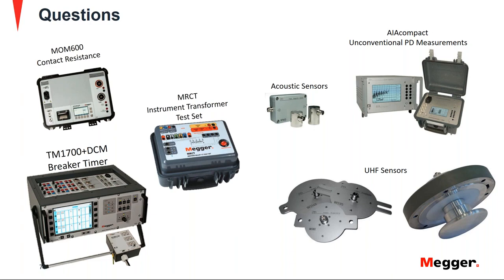Charles, in regards to PD testing on GIS, is online more accurate than manual testing? So I assume that this is either online monitoring, well, online measurements is really all you can do on GIS. So there is no offline measurements on GIS. The only offline measurement that we spoke of was during the sensitivity check that we mentioned, which is in the manufacturing or acceptance process. So I'll go ahead and answer that as far as online periodic versus online monitoring, I suppose, because there is no offline testing of GIS.